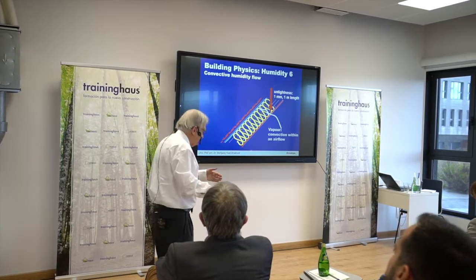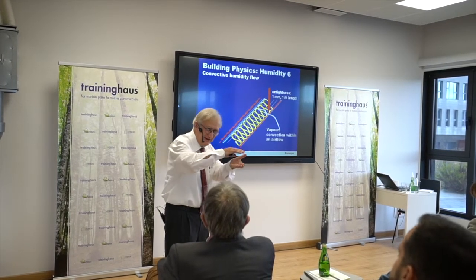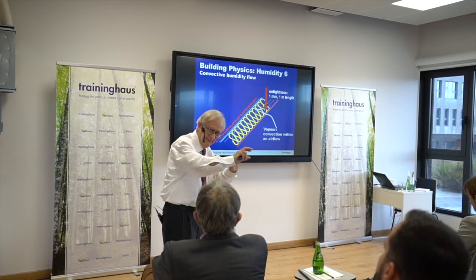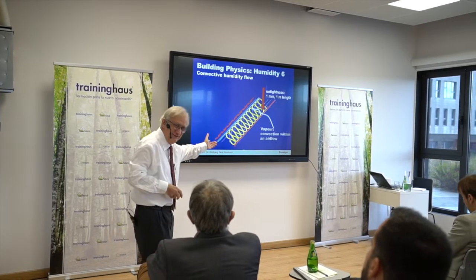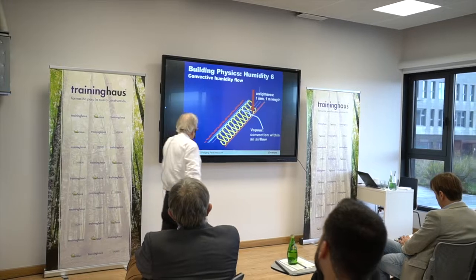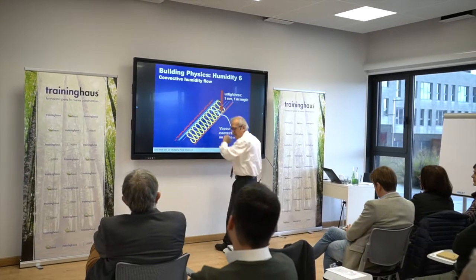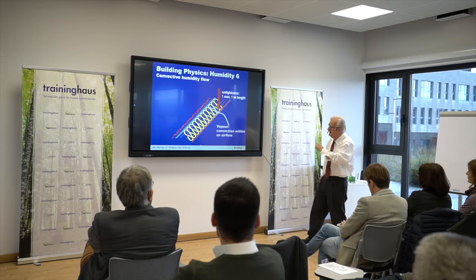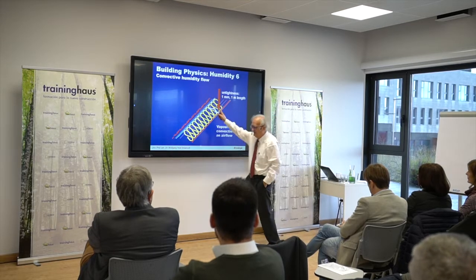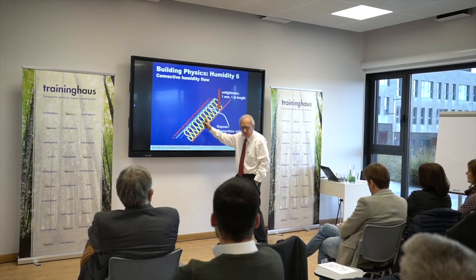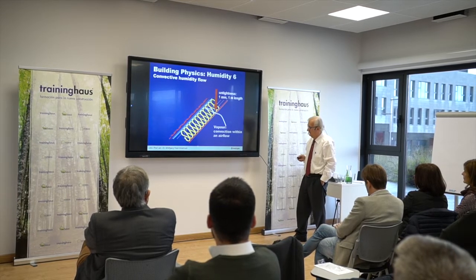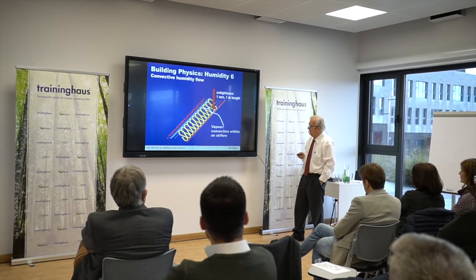It flies because you have under pressure on the upper side of the wing and you have overpressure on the underside due to the dynamical flow. And this is what happens also if you have the wind blowing. You get under pressure on the roof. So yeah, there has to be very, very strong wind to get a positive pressure on the outside of the roof. Normally it creates negative pressure due to this wing effect.